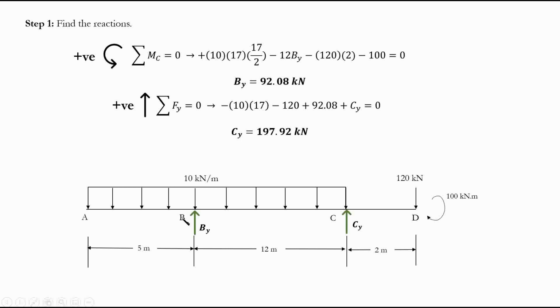Now, if my deflection is 0, that's one compatibility condition. For portion AB, at the end of this portion, I can say that my deflection at B is equal to 0. But what is the other condition? I could say that the rotation for the right portion and left portion are the same. There's nothing really else to talk about. I only have one condition separate from other parts: the deflection is 0 at point B for portion AB.